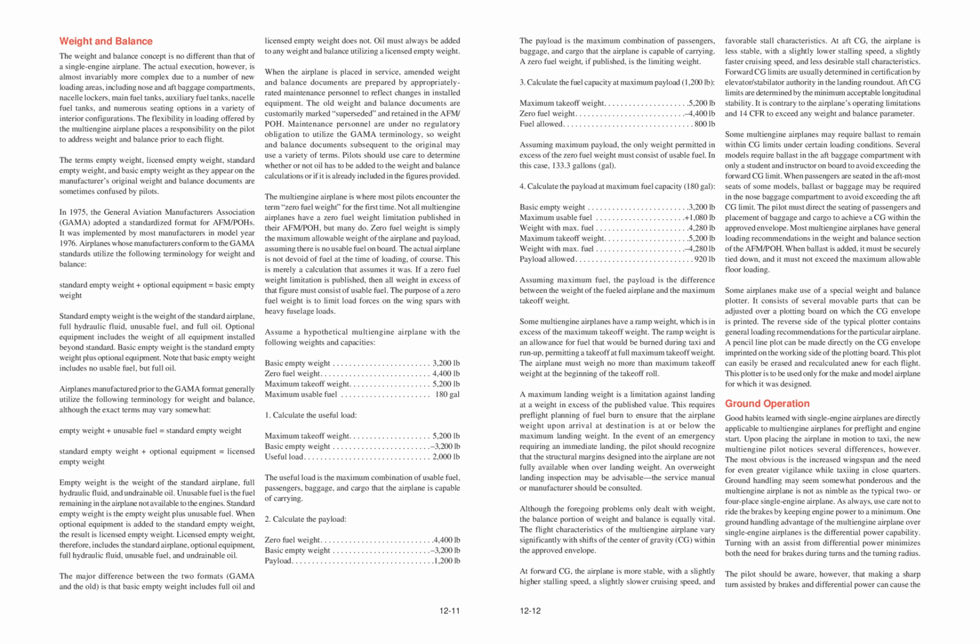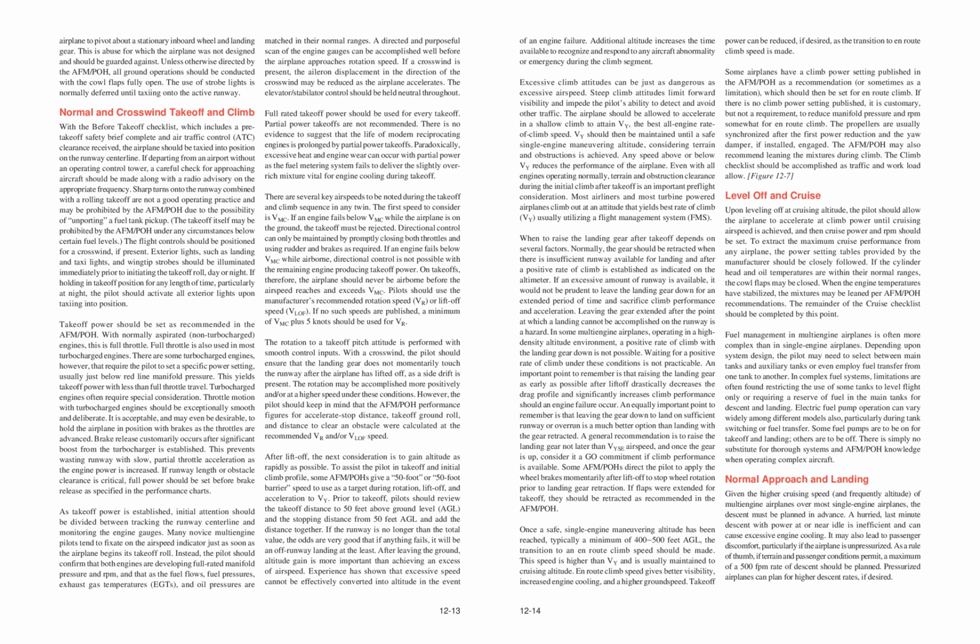The pilot should be aware, however, that making a sharp turn assisted by brakes and differential power can cause the airplane to pivot about a stationary inboard wheel in landing gear. This is abuse for which the airplane was not designed and should be guarded against.